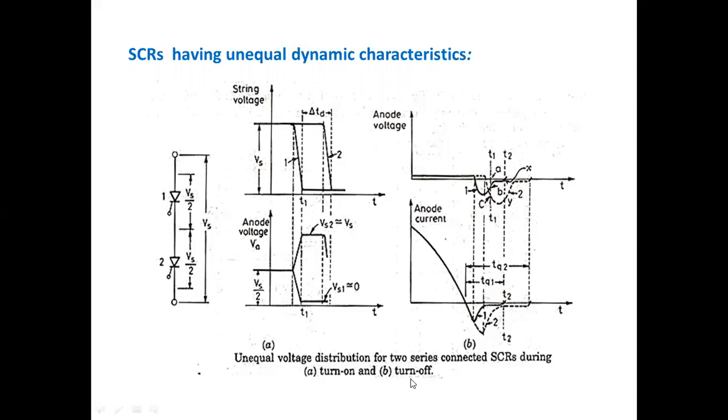These switches are required to turn on and turn off. Nowadays, the main application is BLDC motors, and electric vehicle transportation is increasing. All these brushless DC motors operate using a power drive circuit. This power drive circuit consists of switches such as thyristors, SCRs or IGBTs. Some applications also use MOSFETs, but most applications use IGBTs.